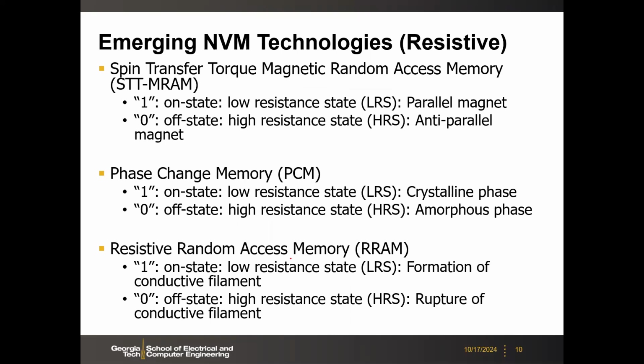Okay, in general, you can call all of them resistive memory. But we split that into three because they have different underlying physics, right? Even though externally, when you observe that, you can abstract all of them in the circuit symbol, like a resistor with an arrow, which means resistance can be changed. All of them are two-terminal devices, right? So basically, you have a variable resistor here. But the physics is different, or the principle is different, right?